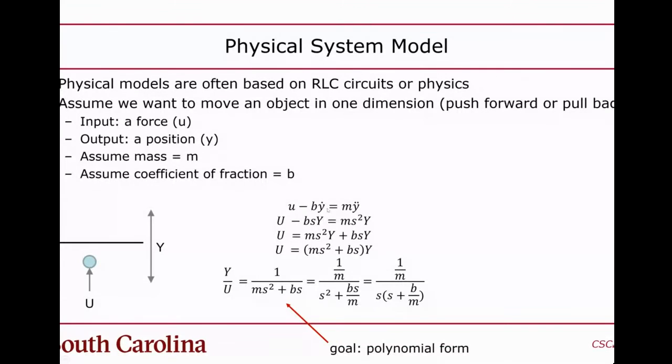it's literally just, you've got u and y, two time series signals, right? And y has a derivative and a double derivative. So all you have to do is convert it to the S domain. I didn't put y of t here, I just said y of S. I took the y dot and made it capital Y to signify that it's in the S domain, and then multiplied it by S to signify that it is a derivative. And this is a double derivative, so this is S squared, right?